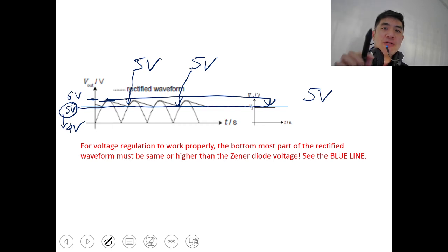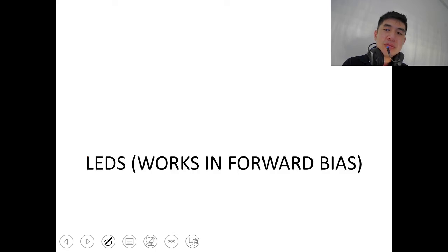It is very powerful for voltage regulation, for converting AC to DC supply. So don't forget to connect the capacitor first, then it will work better. If you don't connect the capacitor, then the zener will turn on and off, and you still have the same problem. So now do you understand how this works? If not, you can revise and revisit my video again if you want to hear me explain this again. This part needs a little bit of thinking to get it right.